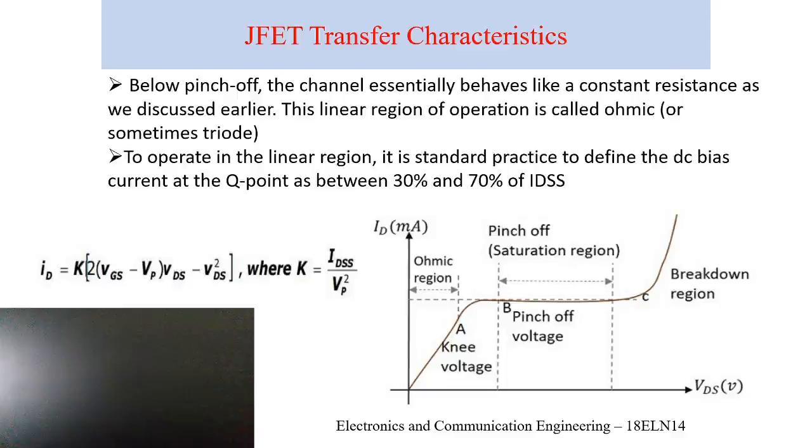However, we have to note that IDSS is a function of temperature, and both IDSS and VP are strongly functions of the manufacturing process. So it is important that, for the manufacturer data sheets, you know at what Q point the data is obtained, for safe operational conditions.